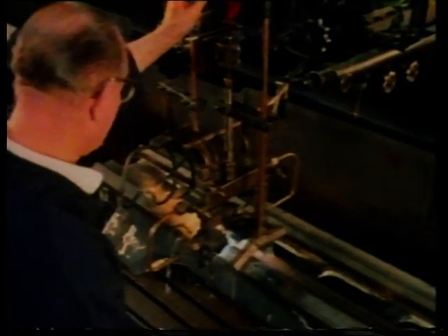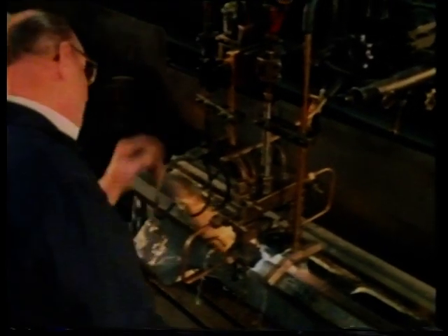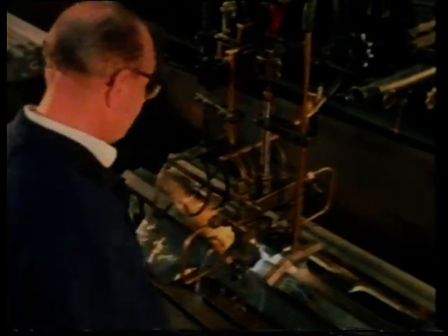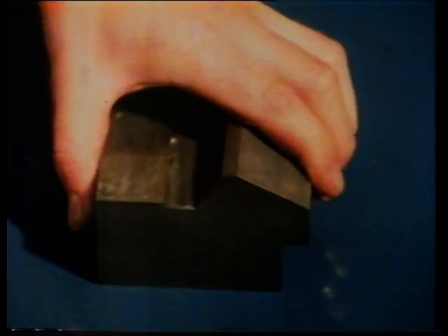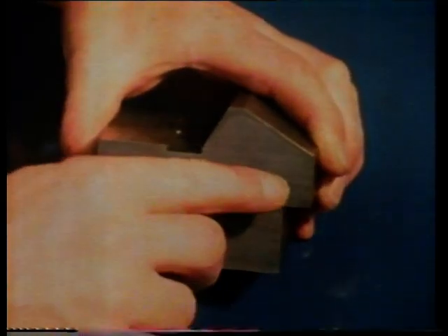We do this by heating and then cooling the material in a carefully controlled way. First, the metal surface is heated to about 900 degrees centigrade, in this case by a row of high-temperature flames moving slowly along the slideway. The hot metal is then cooled rapidly with water. This heating, followed by rapid cooling, hardens this particular material. If we look at a specially prepared cross-section through the slideway, you can just see the hardened area around the edge.